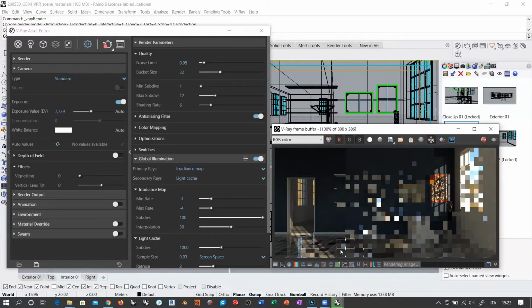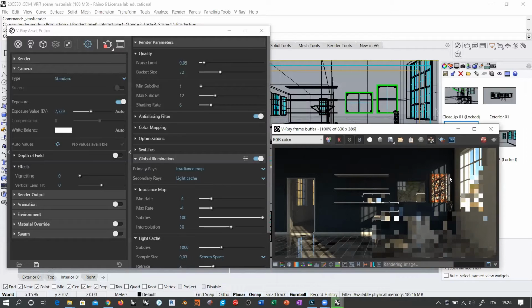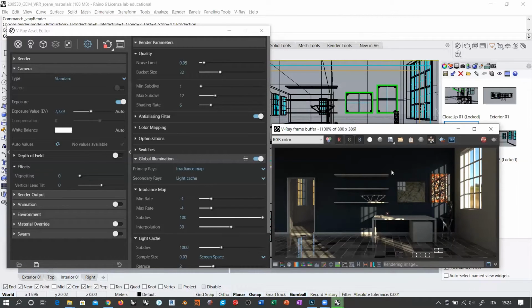But in this case, you can see that because we are already using materials and some effects like reflections and so on, those kinds of problems start to disappear. So you must not always increase light calculation quality, especially if your image is going to go through a post-production process. Then you might render the final image in V-Ray with poor light calculation quality, and take into account that you will have a post-production process that will eventually eliminate any of the artifacts that you are getting here.